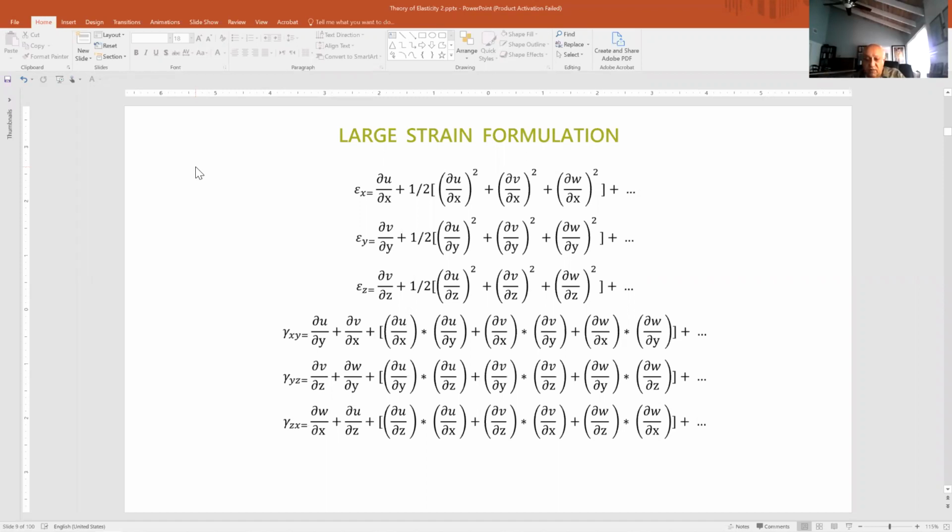Solving these equations would take much longer time, and it is done by iteration, and we may end up with situations that it may not converge, and we have to work through the problem. So a problem that may take a few seconds, if we are assuming a small strain, may end up a week or two working to arrive at a reasonable solution for large strain.